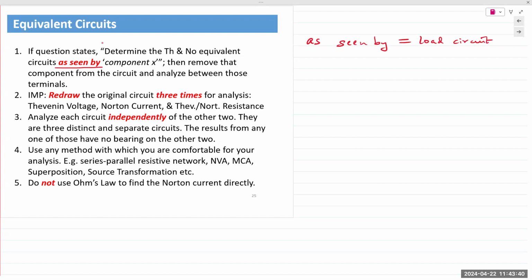Electronic circuits are usually multi-stage operations. As an example, simple audio equipment, you would have a preamplifier followed by an amplifier followed by a speaker. The speaker is actually the load for the amplifier, but the load for the preamplifier is the second stage, which is the amplifier. So preamplifier, amplifier, and speaker. Each succeeding circuit or each succeeding stage is the load for the previous stage. So the speaker is the load for the amplifier is the load for the preamplifier.